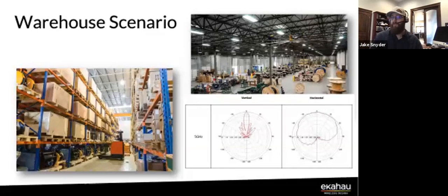But a moderately wide patch, like a patch that's, let's say, 90 degrees, 40 feet in the air, definitely has a lot of properties that are going to look more like an omnidirectional from the ground perspective. So maybe I don't use a super narrow patch like a 30 degree, but maybe I use a 90 to 105 degree patch. Keep that RF energy going the direction you want it, and still cover a pretty healthy wide area.